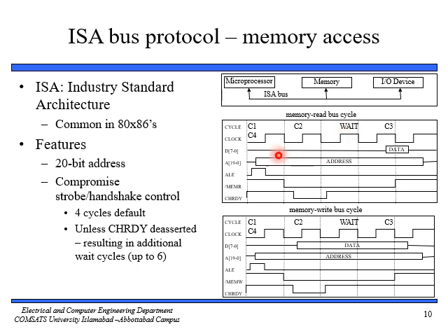Initially we are putting the address on the address line, and then we are latching the address because we are going to keep this address on the address line all the time, C1, C2, C3. So we have to latch this, and then we have the memory read signal to request a read operation.